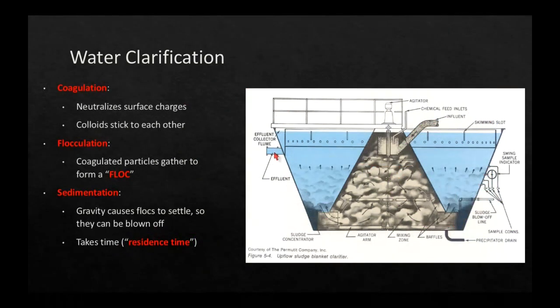Okay, so then the last thing I want to talk about with this is the chemical feed. How do we know how much chemical we've got to feed? Well, we're going to put a control valve there on the chemical feed line. Or actually, probably what we're going to have is a pump that starts and stops.